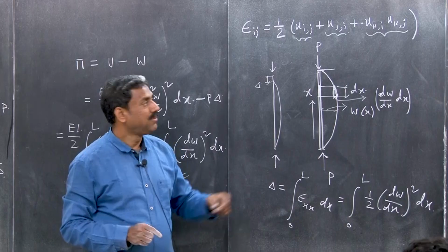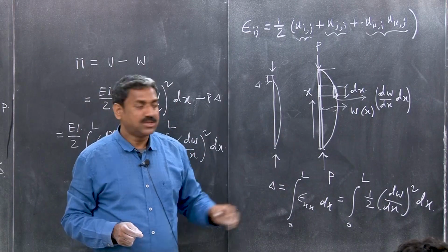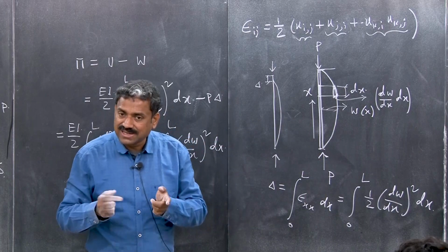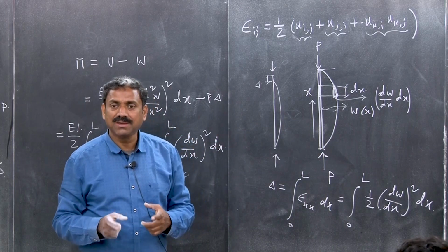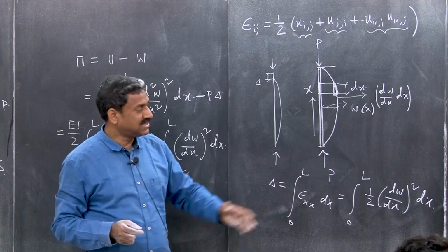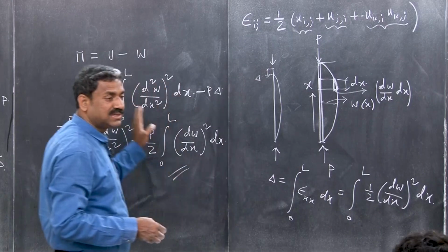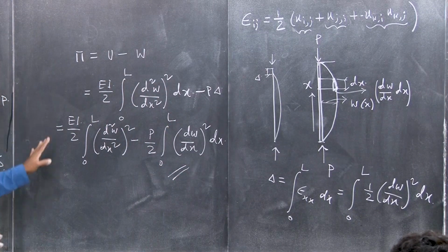You understand, right? Because in du/dx, there is no u, no in plane deformation, but still there is in plane strain. Why is it happening? Because the in plane strain is occurring due to out of plane deformation, and that is described by von Karman nonlinearity. Clear? So, this is the functional expression for the strain energy.